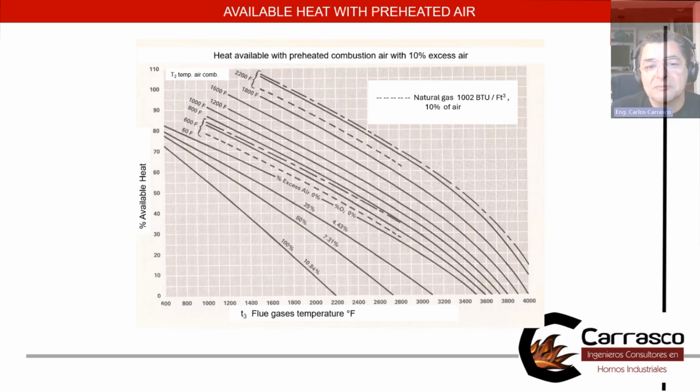preheating the air costs money because the material has to be stainless steel. These materials can stand higher temperatures and become more expensive. And as a furnace manufacturer, the selling price of a furnace is always something I have to be aware of, because I cannot sell the most perfect furnace since it's not going to be competitive. So I have to keep a balance between how much I want to use in good materials and how much is going to be good enough to sell the furnace to my potential customer.